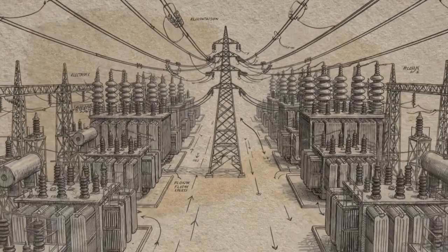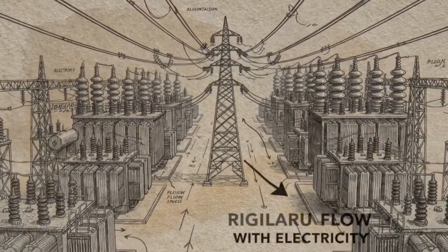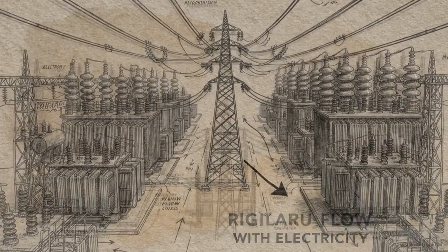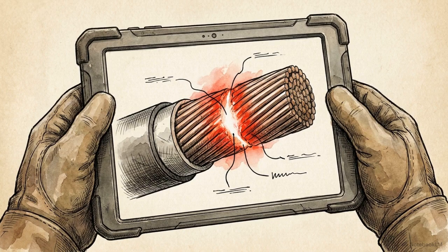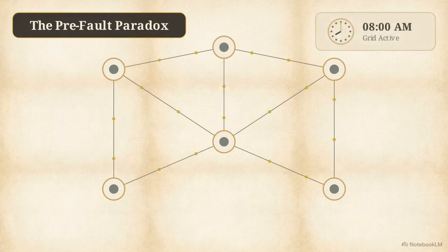To maintain a stable grid, every piece of protection hardware must be sized for a specific worst-case scenario. This requires engineers to calculate the absolute maximum short-circuit current that can flow into a fault. Standard superposition methods hit a wall. The grid constantly shifts, changing every minute. Introducing a fault here makes the current dependent on the exact millisecond it occurs.